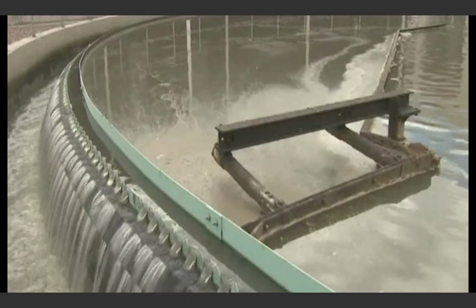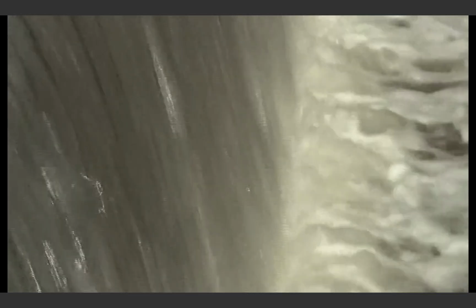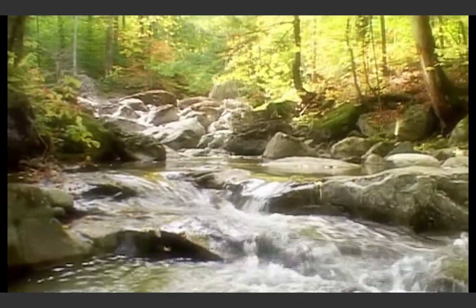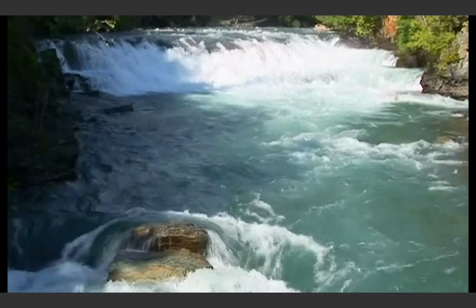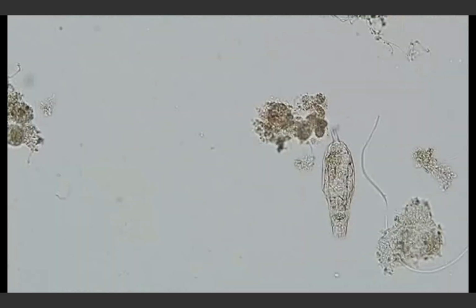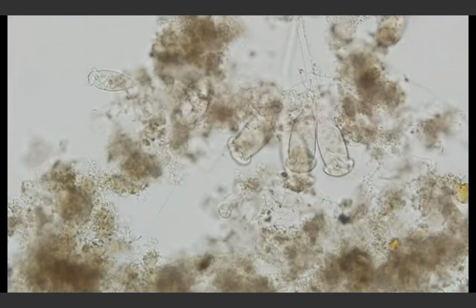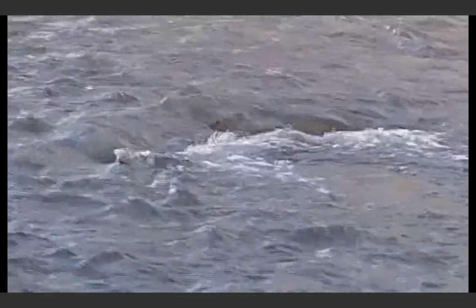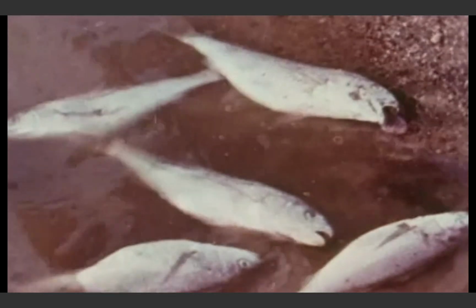Both are removed in the wastewater treatment process, but removing that very small dissolved solids portion is the focus of wastewater treatment. Wastewater treatment speeds up what happens naturally in streams and rivers. In these waters, bacteria and other small organisms will feed on waste, eliminate waste, and produce new bacteria cells, carbon dioxide, and other products. These waste-eating bacteria consume oxygen during this process. Aquatic life needs oxygen to survive. Nature's balance is tipped when the amount of untreated wastewater exceeds the natural water's ability to purify and ultimately support aquatic life.